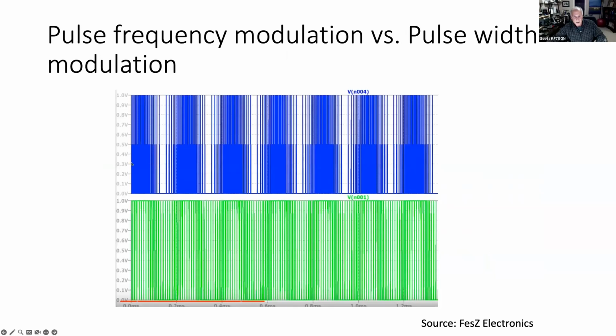So once you've done that, this would be a picture of a repetition of the sine wave in the pulses. In this case, I think this would be a pulse frequency modulation, where you get something that almost looks like a frequency modulated wave. But it's just a bunch of pulses that are either bunched together or spread apart, depending on whether the sine wave is positive or negative. The positive portion of the sine wave would cause the pulses to bunch together, and the negative swing would cause the pulses to move apart from each other. Where the minimum of the sine wave occurs, you get the biggest separation between the pulses, and the maximum of the sine wave would occur where you get the most dense bunching of the pulses, if you want to call it that.